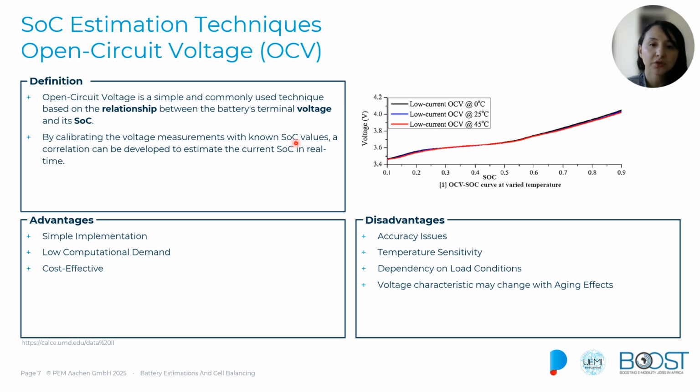So we need to be sure that the measurement, for instance the voltage sensing network we are using, is as stable as possible, even in variable temperature conditions. Once we have the value of the open circuit voltage, we can use different lookup tables or equations that correlate both parameters. In that way, we can obtain the related state of charge.